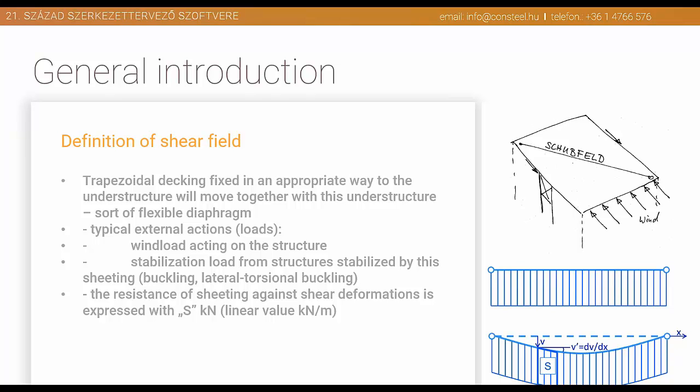Now, traditional engineering practice was to completely disregard the load bearing and stabilization effects provided by roof elements. Roof elements are typically just designed to transfer the vertical loads to the underlying supporting structures, like snow load, wind load, and such. And of course, the engineer is aware that something is still in the structure, but usually it's only considered as a load, with its self-weight as a load increase, and its stiffness is not considered as something which would help the structure to resist the external loads.